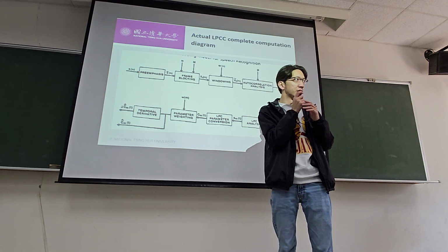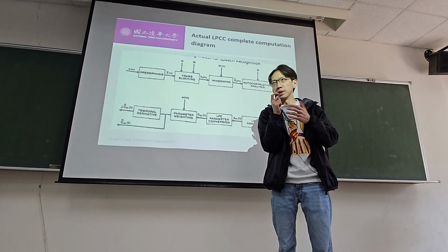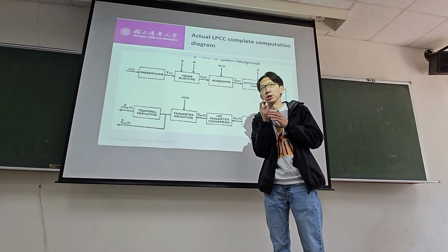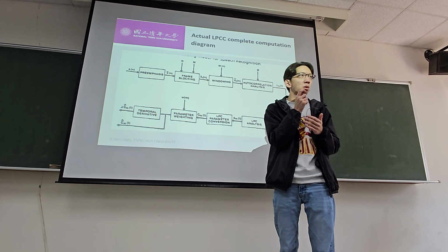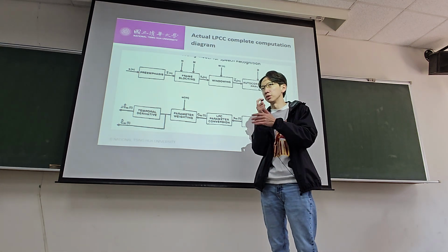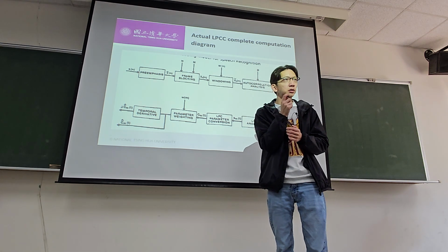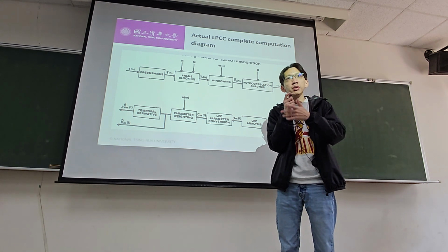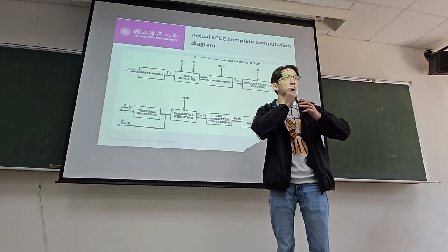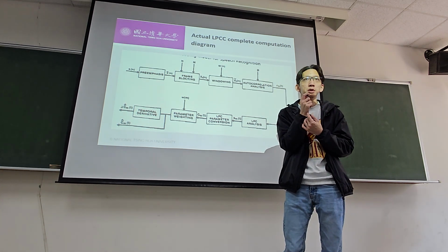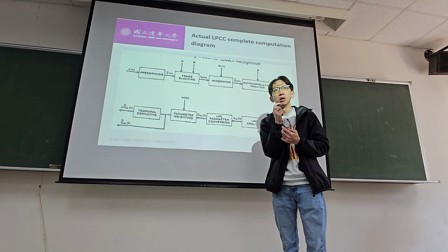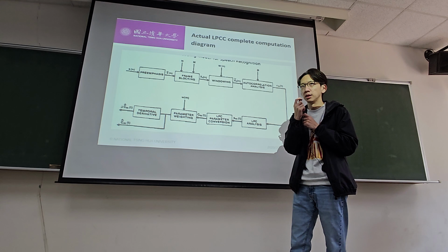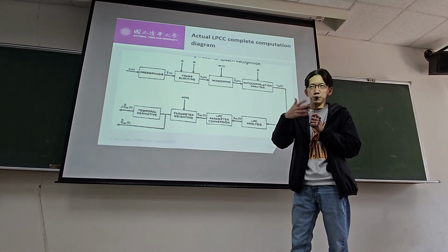So about speech analysis, we started with speech production, understanding the time domain, frequency domain analysis, now into a linear prediction model, which tells us the filter part, and then move into cepstral analysis again, trying to tease apart source and filter through the cepstral transform. Now we're moving into a space that starts putting all these tools together to derive coefficients or features or representations of the speech signal that can be further used as input for other speech technology. Okay, so LPCC is one such feature extraction, or we call it speech features extraction.